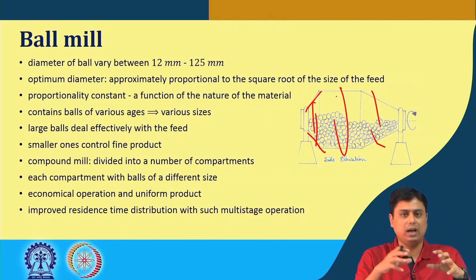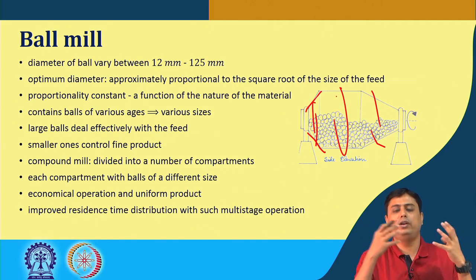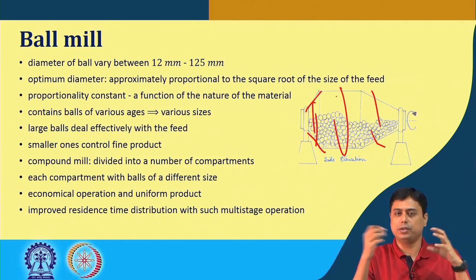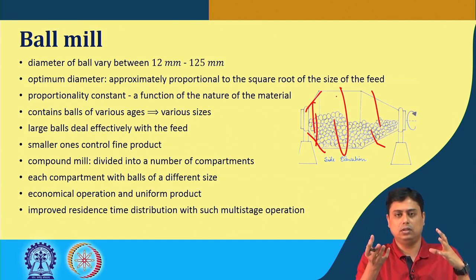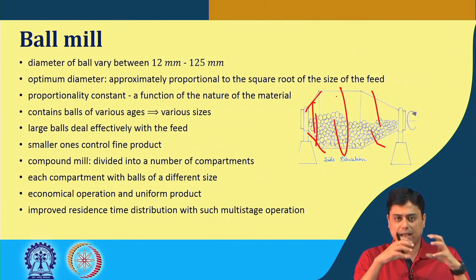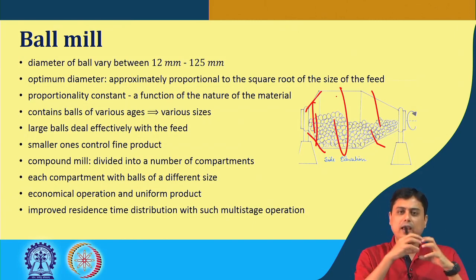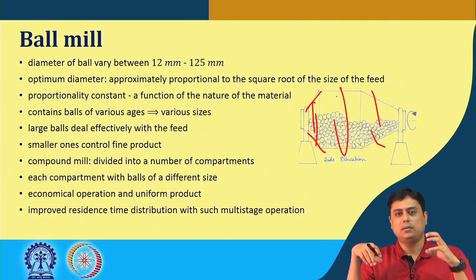So, even if we start with uniform size balls, they will be of different sizes after several operations due to this wear and tear, and that is helpful, because with different sizes effective grinding can happen.